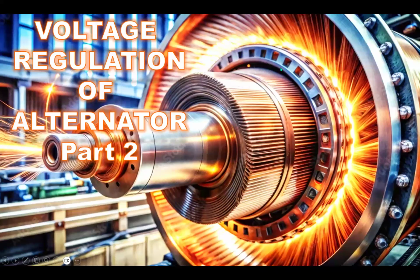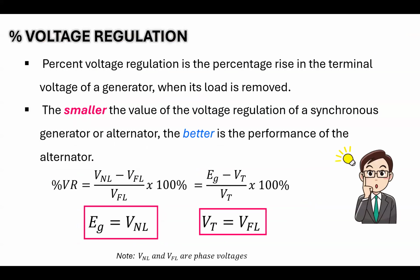Today we're going to talk about the voltage regulation of alternator. This is the part 2 of our discussion about the voltage regulation. So again, the percent voltage regulation is the percentage rise in the terminal voltage of a generator when its load is removed. The smaller the value of the voltage regulation of a synchronous generator or simply alternator, the better is the performance of the alternator.